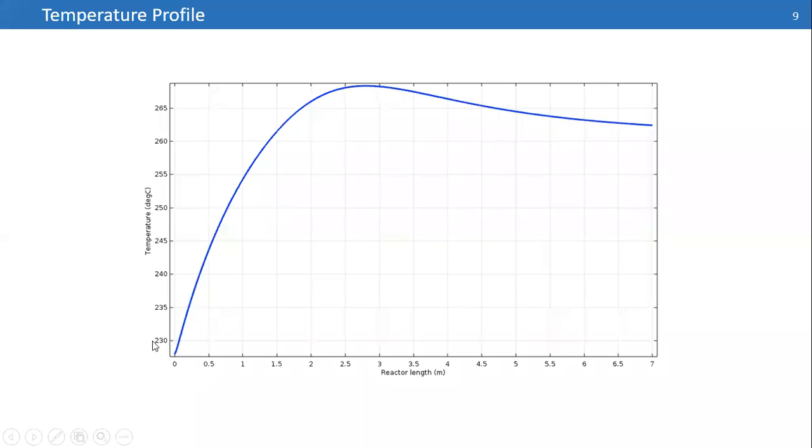When the temperature is lower than this value, 250, let's say on average, or 260, you can see that the kinetics is not strong enough to proceed with your reaction. And when you increase temperature, since the reaction is exothermic, high temperature is not favorable. So you are going to have a lower yield of methanol at the outlet of your reactor. So it would be another problem.